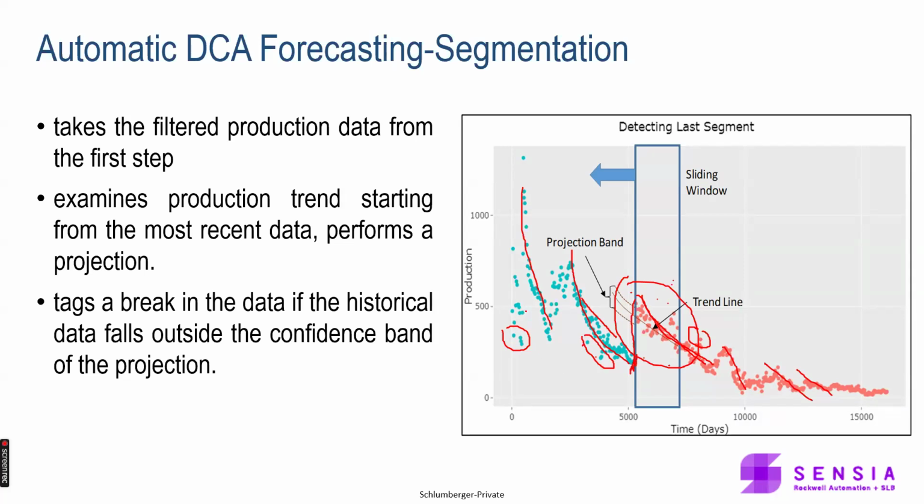For example, if you have ESP wells, those ESP wells will have a problem if your gas oil ratio increases because you are reaching bubble point pressure. So automatically it will tell you when you should trip your well, and when you will reach your bubble point pressure. We have a very good case study where we saved the company 120,000 barrels per day just by applying this workflow without drilling a single well. Okay.